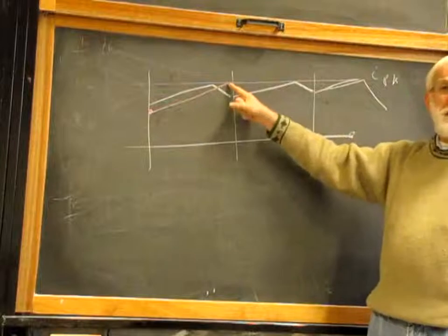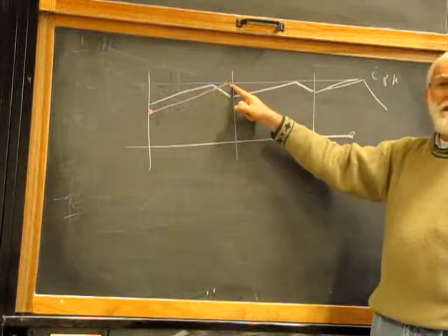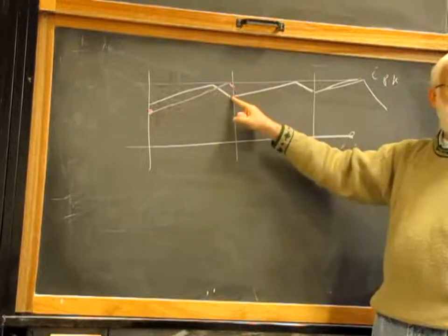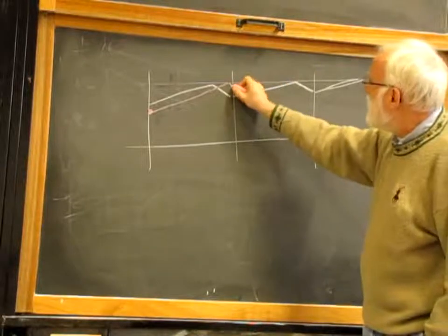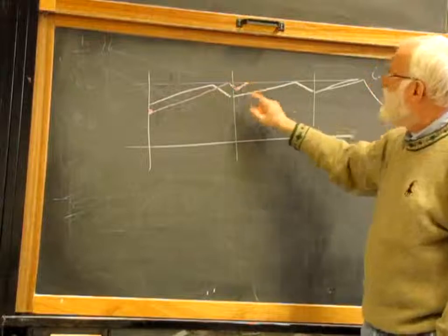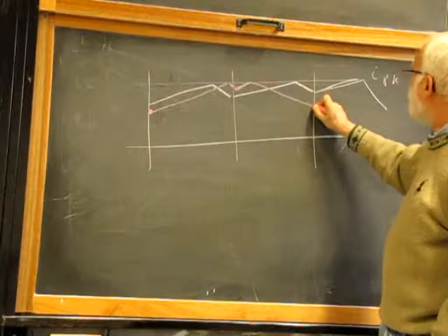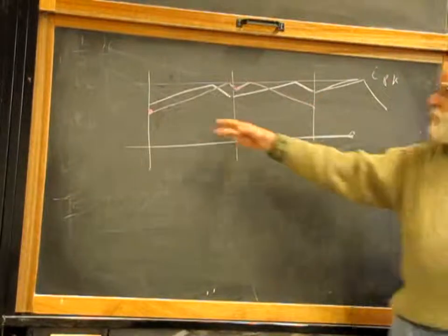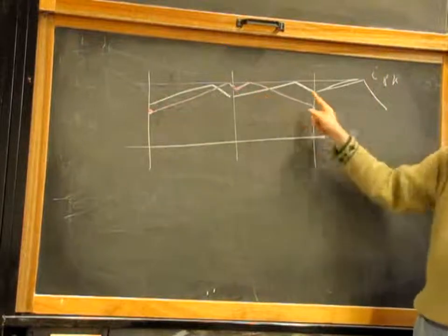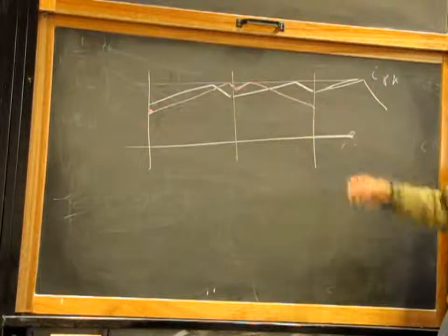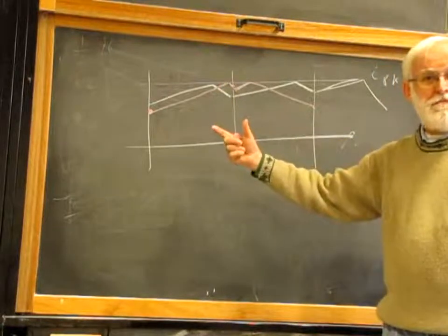The peak control keeps the peak at the same value. But doing this, I end up with the final current that is too large with respect to what I want. So the next cycle will start with a current that is larger than this. It will reach immediately the peak value and will come down over here. Ouch! We already determined that this amplitude becomes larger at the end of this cycle, becomes even larger at the end of this cycle, and we are in a condition of diverging error. Why? Because the duty cycle is larger than 50%.